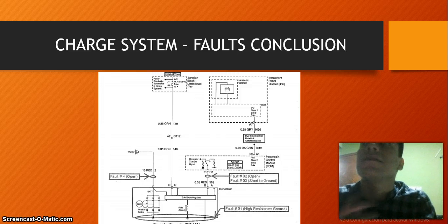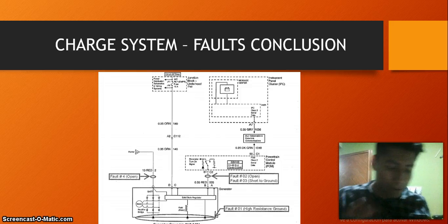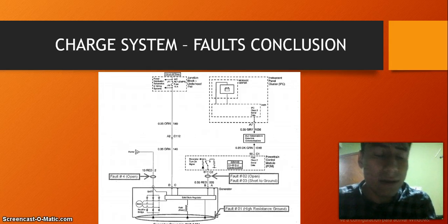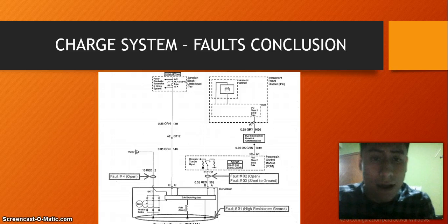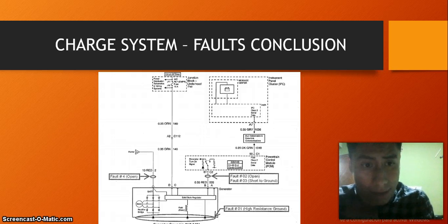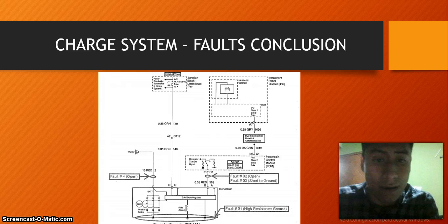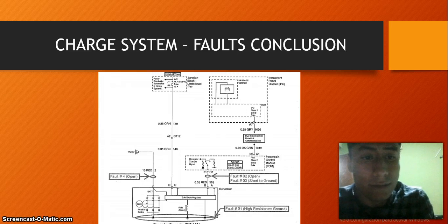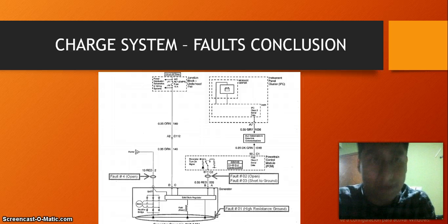As analyzed, this component generates electricity in the following way. First, the rotation of the engine crankshaft transmits movement to the alternator through the rubber belt. Then the rotor inside of the alternator rotates inside the stator windings. The rotating movement of the rotor generates electricity in the form of alternating current, and finally the rectifying diodes convert this alternating current, AC, to direct current, DC.